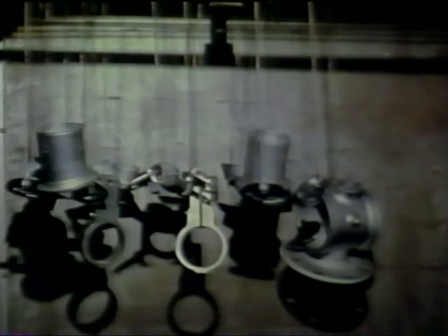In this oven, cadmium-plated parts are baked at 350 degrees for a period in excess of 3 hours. This procedure drives off the hydrogen atoms within the metal surfaces. This will eliminate the possibility of future metal crystallization and component failure. The hub components are now ready for reassembly. Let's leave them and go back to follow the blades through their overhaul process.